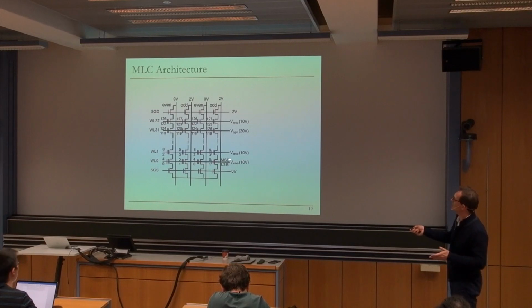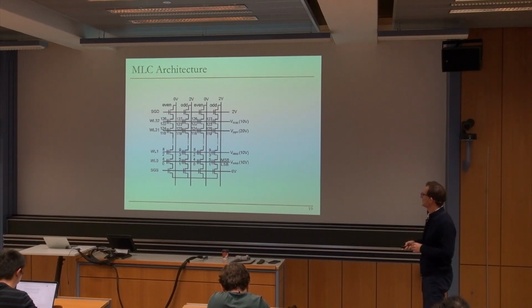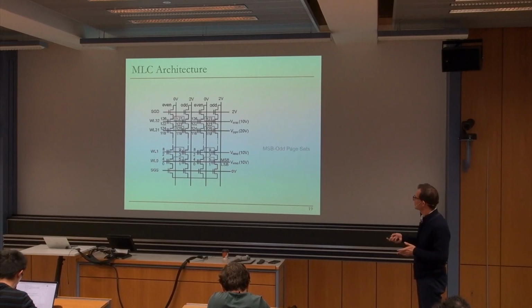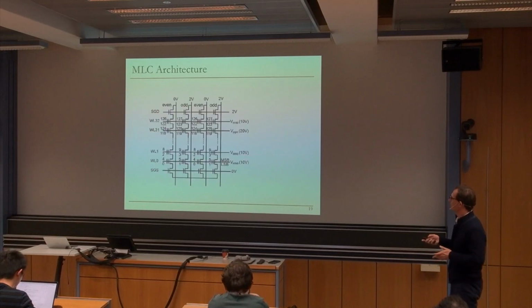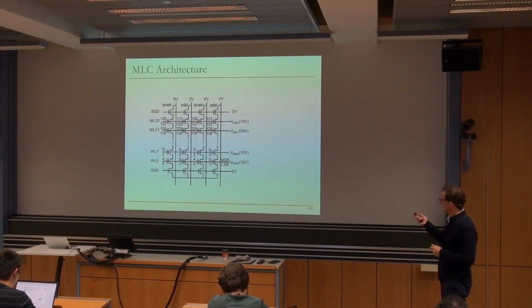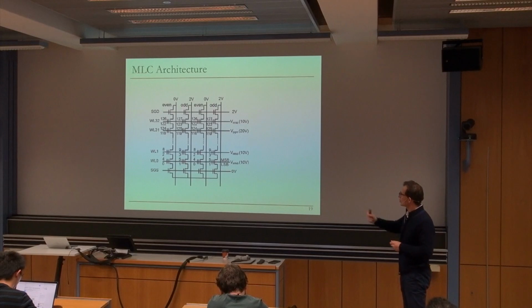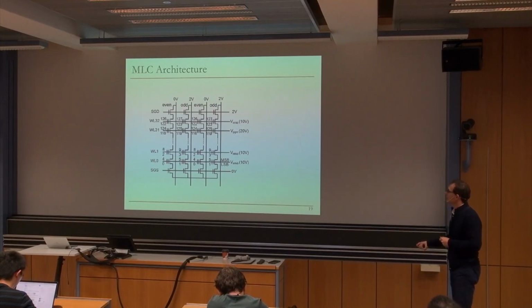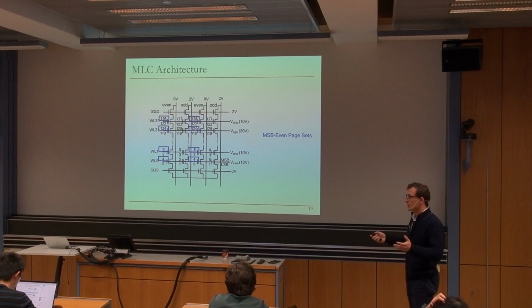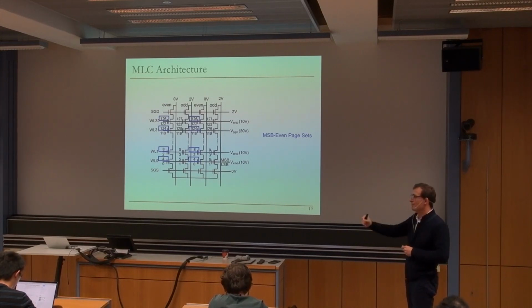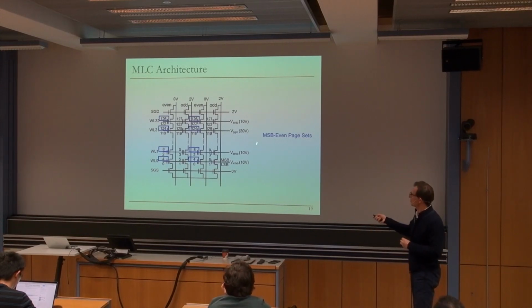You can see the MSB and LSB over here also. That's fine. But basically, if you see these figures, you should think about corresponding these to these states over here. One thing that I will talk about over here is that the order in which you program things matters. As I said, this is LSB odd page sets, MSB even page sets. So the order in which you program things matters, because whenever you program, you cause interference to the adjacent word lines because of these voltages that you apply.